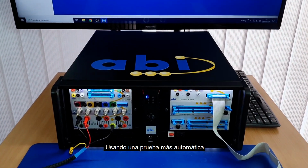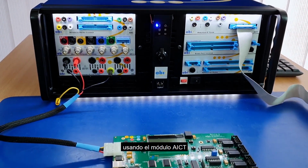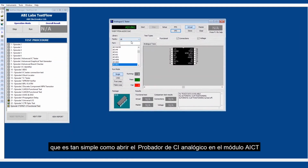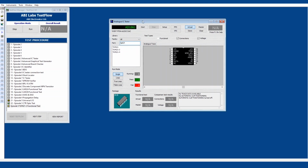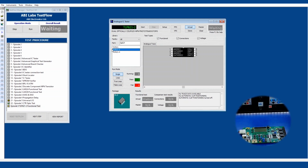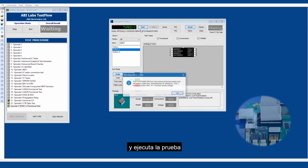Exactly, so using more of an automatic test, we'll now test the functionality of the optocoupler using the AICT module, which is as simple as opening up the analog IC tester in the AICT module, searching for our device, which is a TLP621, and there it is. This is the one we want, and it gives us a handy readout about the device, a dual coupled NPN phototransistor. And it gives us that it's the DIL package. That's our IC there. Just need to hook onto the IC, as simple as that, and run the test.